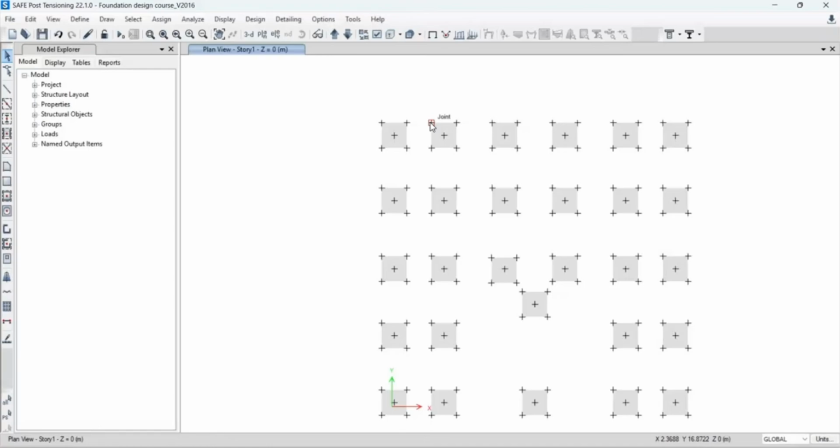Okay, but here's the thing: FEM, which is finite element method, cannot analyze a large blank geometric shape all at once, right? How does it work? It works by dividing that large shape, right? You can see this large footing slab shape. So it works by dividing this large shape into a network, or we can say into a mesh of hundreds of small interconnected elements, and these are usually square or rectangular elements.